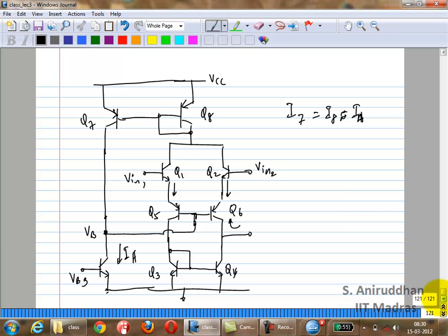Okay, so suppose I have the differential pair, the normal differential pair. You fix the emitter voltages to be the same. Actually, you don't. If there is mismatch between them, it will never be equal, right? The minute you have mismatches, in the case of a differential pair, also the common emitter is not a virtual ground, because the two sides are not symmetrical. Isn't that right? This one is not that different. It just happens to be a common source follower instead of a common source, but emitter follower instead of a differential pair common emitter. That's all.